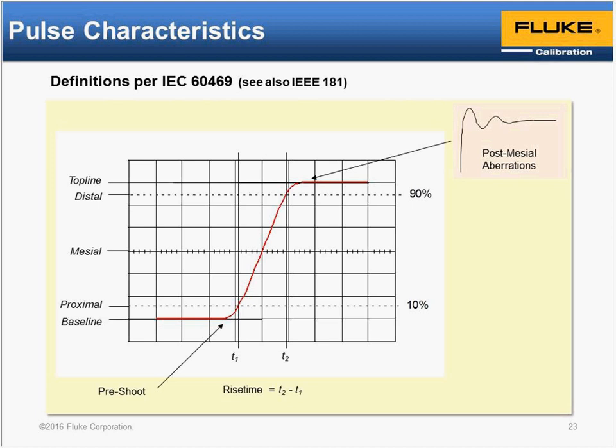There could be some kind of pre-pulse ringing or undershoot going on, and if you think of that for a moment, well, how can something happen before the edge transition comes along? That might be a bit puzzling, but if you stand back for a moment and think that the way that these pulse generators work is that there's a pulse generated somewhere inside the pulse generator that probably then goes through some additional circuitry before it reaches the output. So there are transmission lines and other things going on where there can be delays.